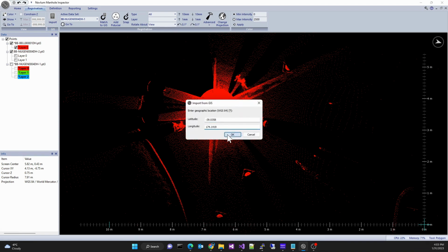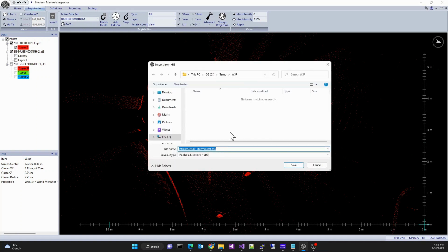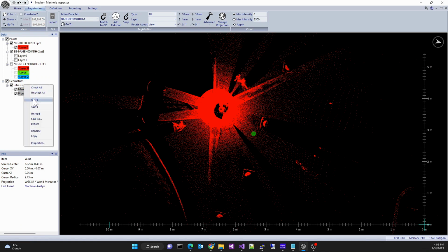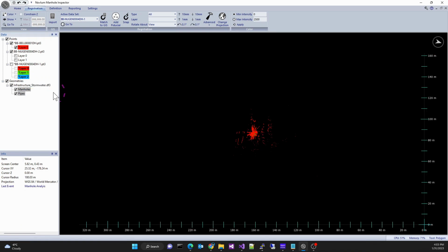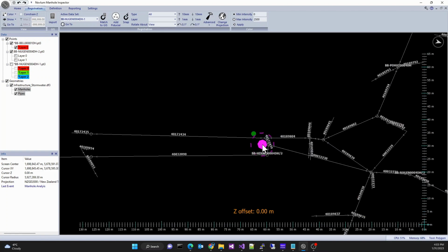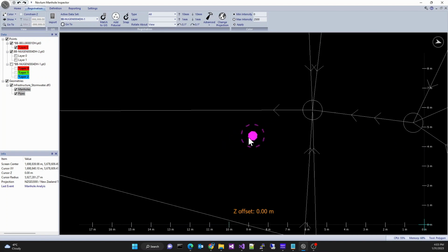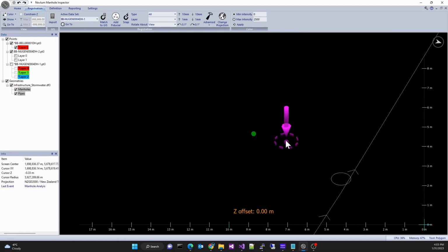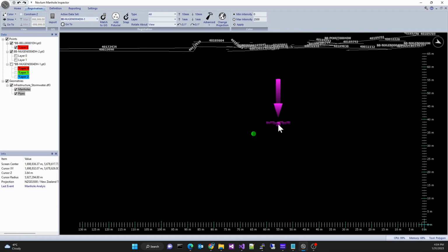The downloaded data shows up in the contents tree window on the left. I can view the data by checking off the layers and then right-clicking Go To. Note that the data is in the NZGD2000 projection in the info window. Zooming in, pipes are shown by lines and manholes are shown by 1 meter circles and do not correspond to the actual diameters of the manholes.